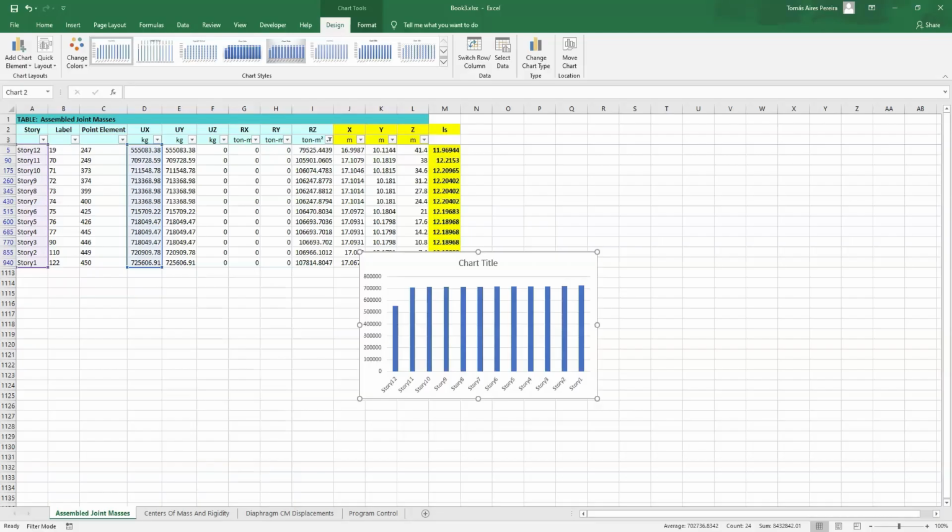An additional point I should mention: these abrupt changes that shouldn't be found in the structure are one aspect, but the Eurocode also tells us that the changes we find should generally be in a descending direction. That is, as we go up the floors, the stiffness and masses should decrease, and these changes should not be abrupt. Even if changes aren't abrupt, if the stiffness or mass starts to increase as we go up the floors, then regularity in height is no longer verified. It is not just about having smooth transitions. It is about ensuring we primarily have decreases rather than increases. We can have a small increase, as occurred at the roof level, but we should not have significant increases. That concludes the topic of regularity in height.